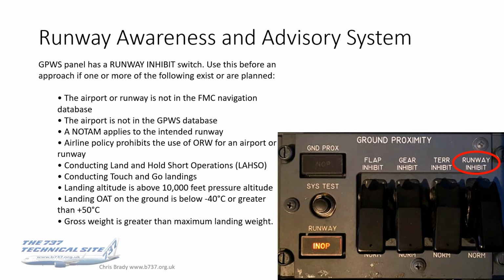And I've certainly had this a couple of times in my flying career where the GPWS has been screaming at me when I've been approaching a good, albeit brand new runway. The airport's not in the GPWS database. A NOTAM applies to the intended runway. Again, seek your company guidance as to what that NOTAM might be.